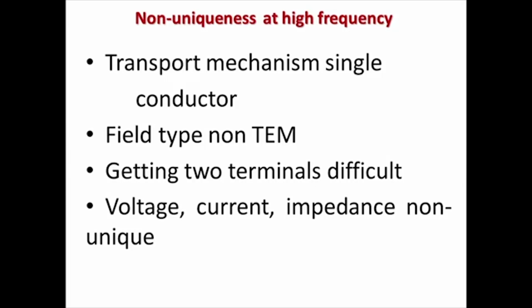So, a single conductor does not support transverse electromagnetic or quasi TEM type of waves. So, the field here is non-TEM, mainly in the form of various combinations of transverse electric and transverse magnetic modes. And in a single conductor like a waveguide, it is very difficult to get two terminals to define voltage or current.